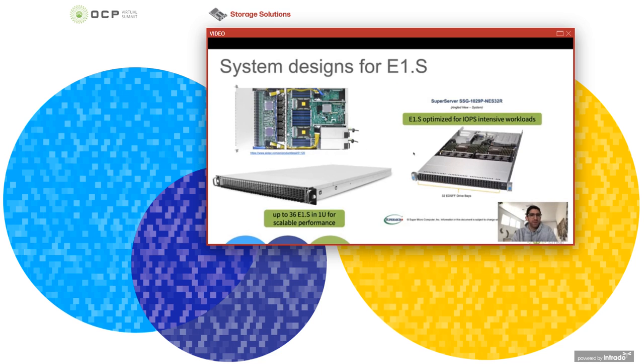I'm going to give a few system design examples for what's out there on the market today. As I mentioned, the 15 millimeter just got released, so there's not really any products out there in the market today, but there are going to be people showing off new platform designs and some of the new capabilities for the 15 millimeter E1.S form factor. But you can see here, this is an example of an AIC platform that supports 36 E1.S, and these are 5.9 millimeter devices in a carrier, and they have their own latch in a 1U platform. So you can see the CPUs here and the PCIe lanes routed directly to the back lane, and you can see here the switches over here. So this is a super high performance system, 36 E1.S drives in a 1U.